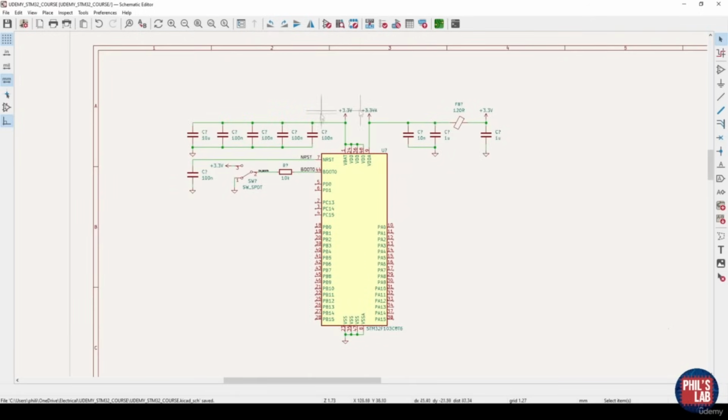So pretty much if we were to supply a power source here to give us 3.3 volts, this will enable this microcontroller to boot up. And this is all the required external circuitry that's actually needed to get this chip up and running. However, this is pretty boring and it won't do very much. What we actually want to do is maybe connect a crystal oscillator to help with timing. This does have an internal crystal oscillator, which isn't very accurate, so we want to add an external one.